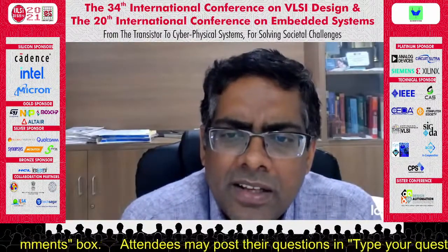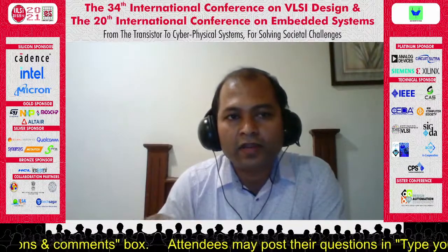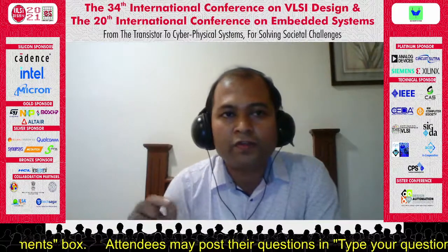Actually, taken from the references, but the way of calculation is that first, for any input circuit, all the inputs are equally probable. So, say for example, if we take a 2-input AND gate, the input probability in both the cases is half, since the number of occurrences of 0 and the number of occurrences of 1 on the input side are the same.